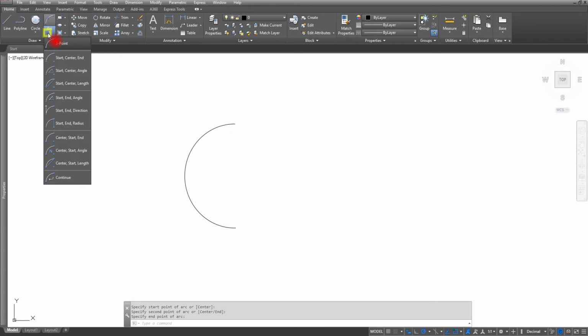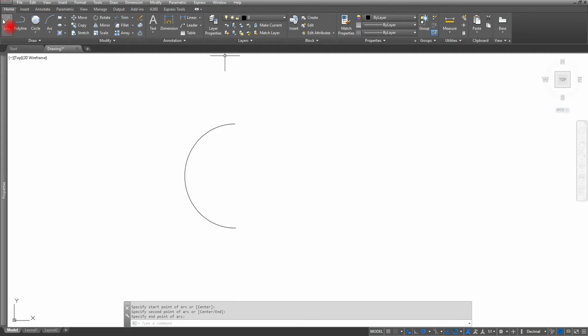If I have something that I want to create and I know certain points that I'm going to select, I'm just going to create two lines that are parallel to each other. So I'm going to draw a line here at 4, escape, a line, and I'm just going to track off of this endpoint. I'll come down a distance of 4, and then I'll continue and draw this line at a distance of 4. Okay, and now I'll hit escape twice.